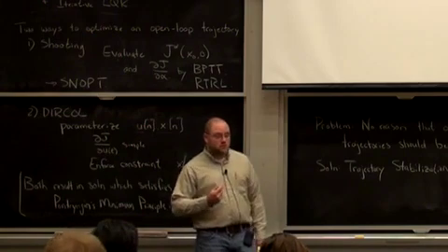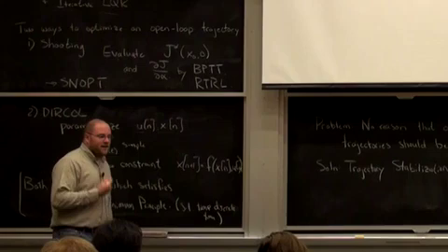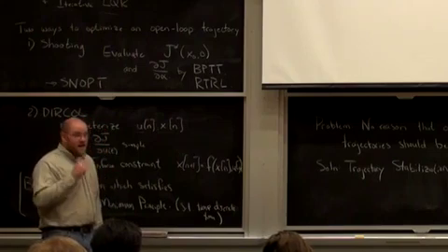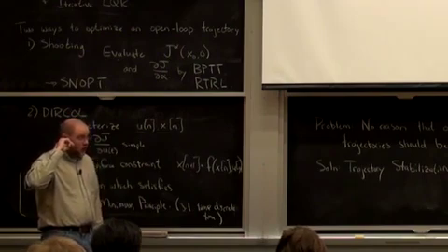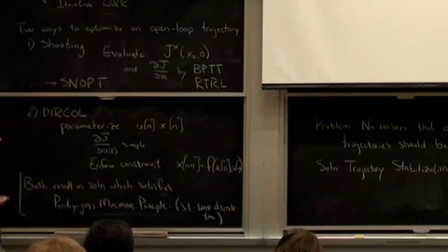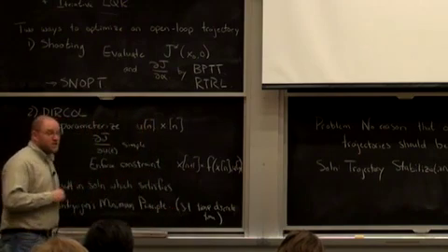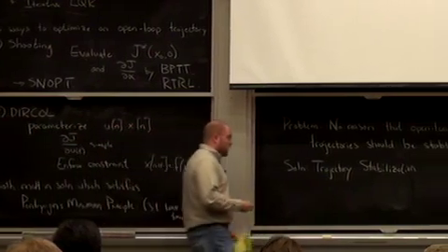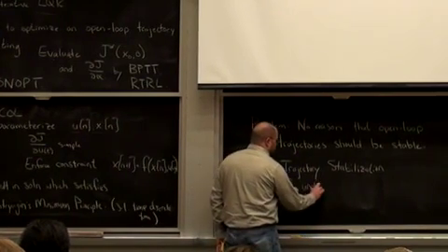in some form. Okay, and all I'll say about it is that the story is sort of the same as everything we've said. If you have a fully actuated system, it's not hard to design a trajectory stabilizer. A good sliding mode controller could work even for an underactuated system. But I think I prefer the linear quadratic form of these trajectory stabilizers. Okay, so we want to do a trajectory stabilization that's suitable for underactuated systems, right?